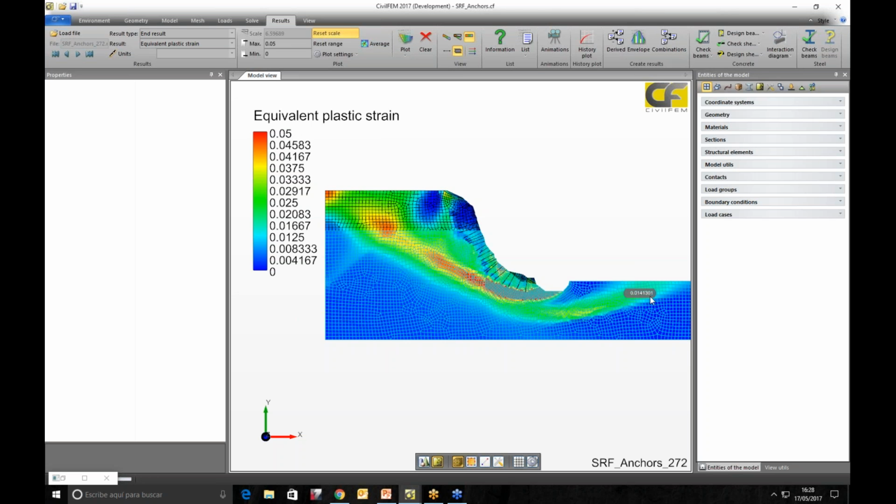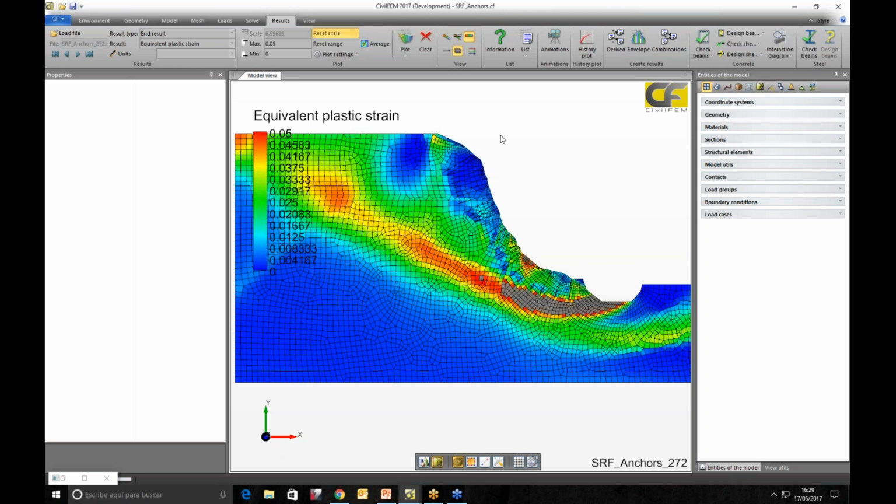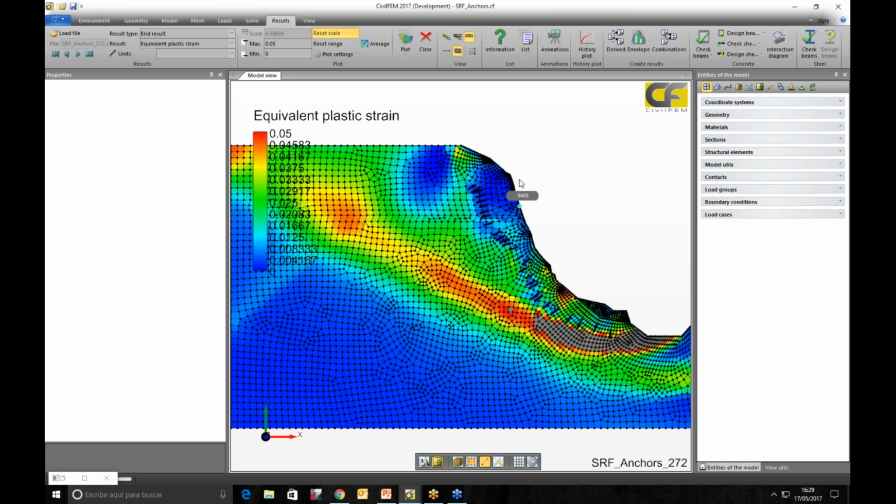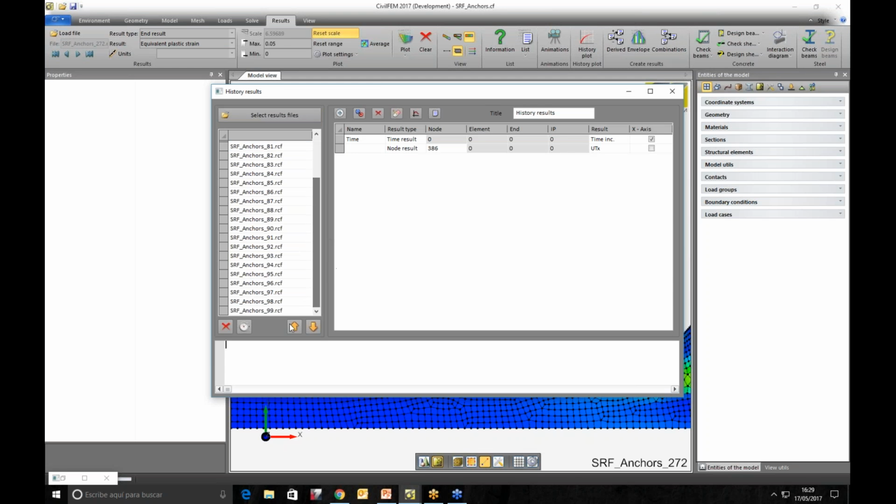This big one through here, another small one that comes here to the river, and also a second cut here. But the one that is yielding is this one. What we saw is that for this safety factor of 2.7, we are having big displacements. So we can plot displacements of one of these nodes versus safety factor, in order to determine a more reasonable, lower safety factor that takes displacement into account. So this node, in example 4441, we will use that node.